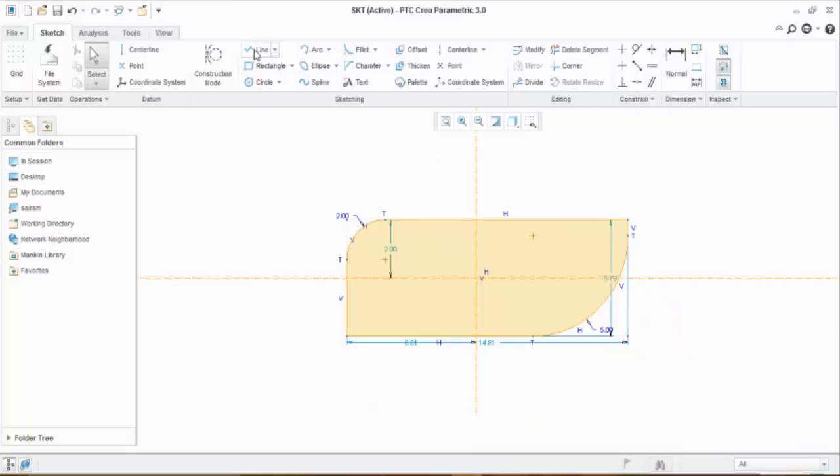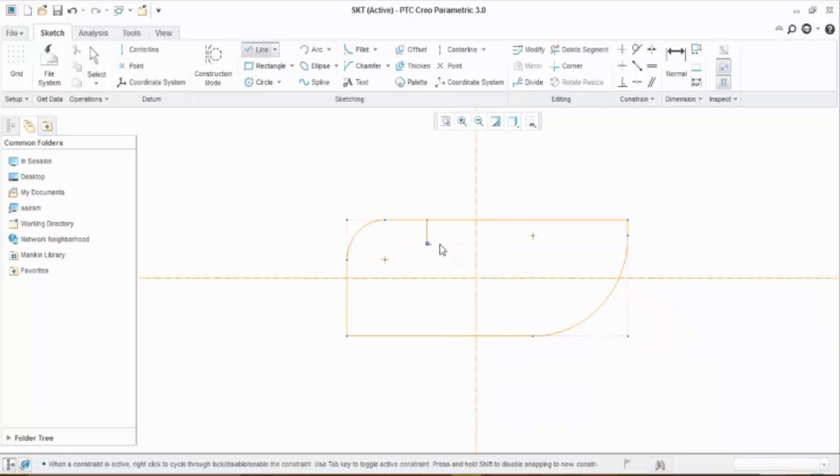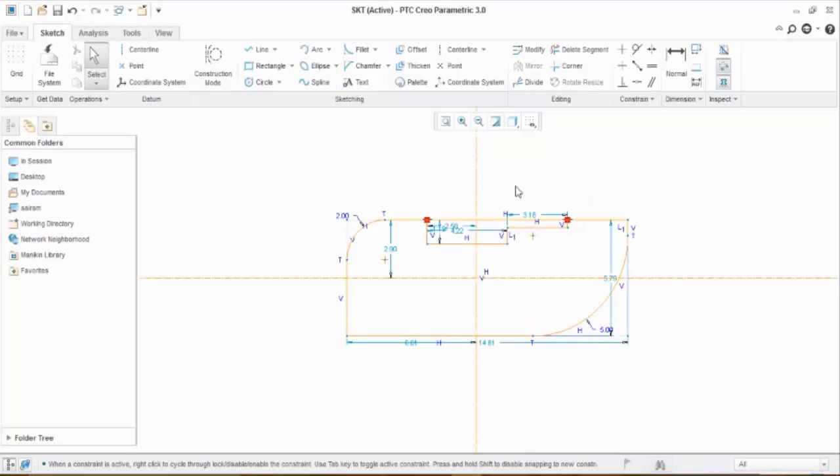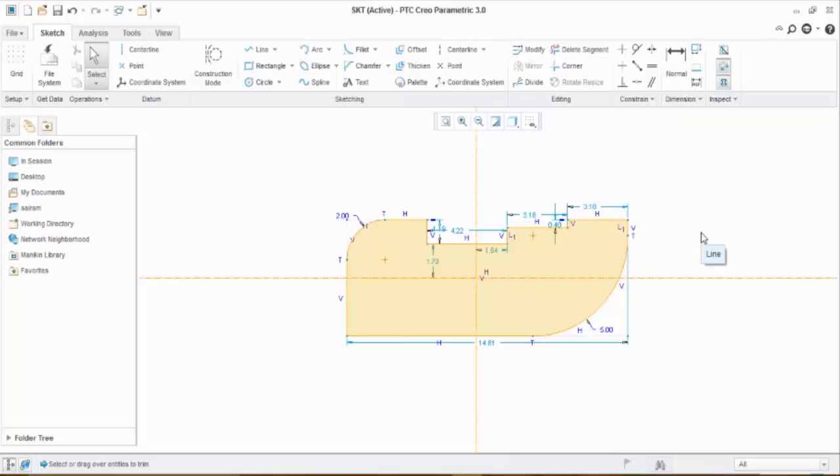If you want to make other changes, just click the lines. Okay, done. We want to trim them, so we can trim them as well. Delete segment is a feature which is called trim. Okay, done. Now if the feature is closed, it will be shaded. Shaded closed loops, right? If this option is chosen, then you can use that.